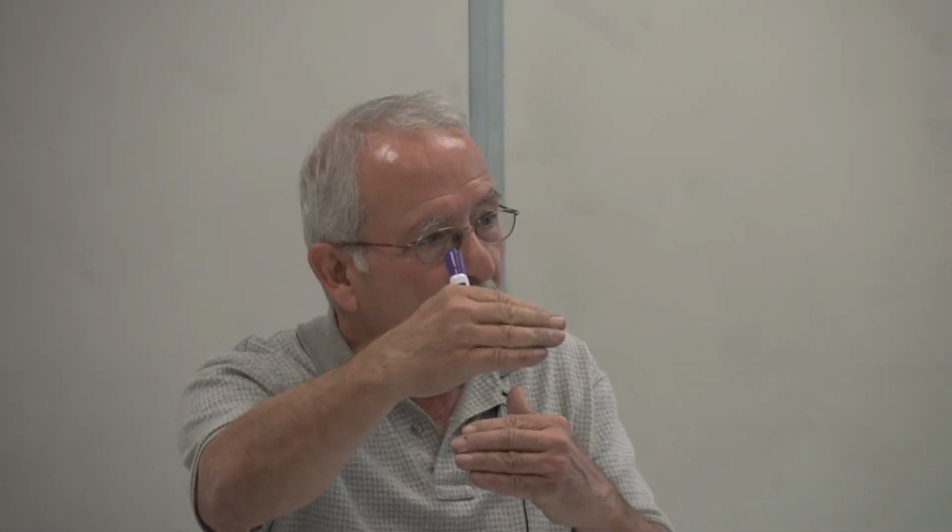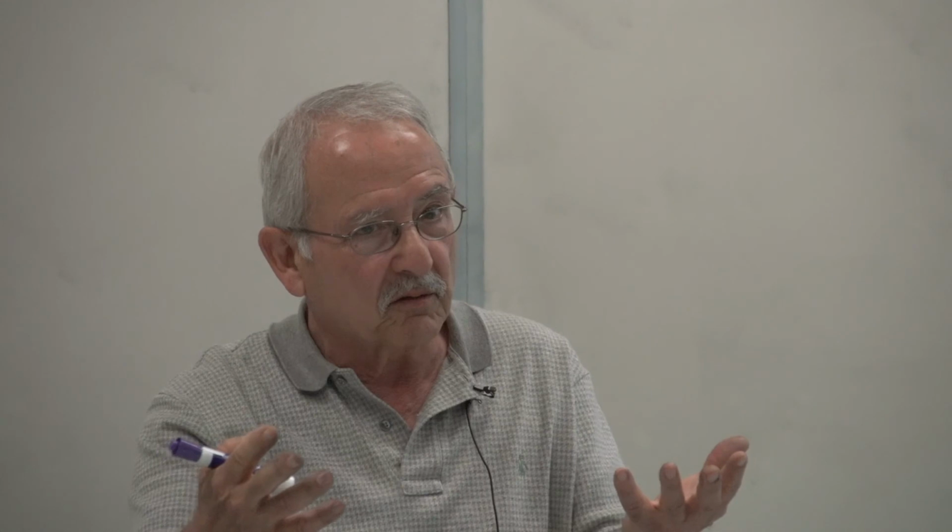Yes? So you started with the yield strength of the material? No, you started with 0. Force was not a constant. You started with 0 force, then you increased it a little bit, then you increased it a little. That's how you got your points and drew the stress-strain diagram. Force is not a constant.